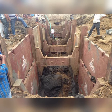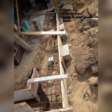Number 3. Dead shore. This system is used when one has to rebuild a defective structure, also to provide an opening in the wall. This consists of arrangements of beams and posts. Beams are placed in the hole which are supported by vertical members called props, that is the dead shore. These are made of timber and are of sufficient section to carry the load above.